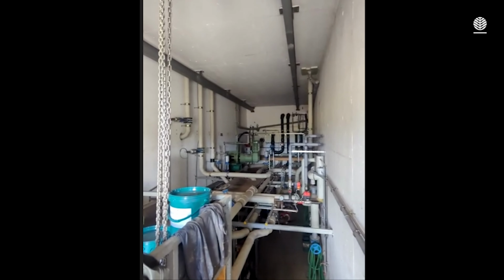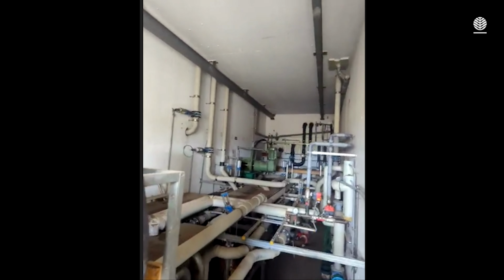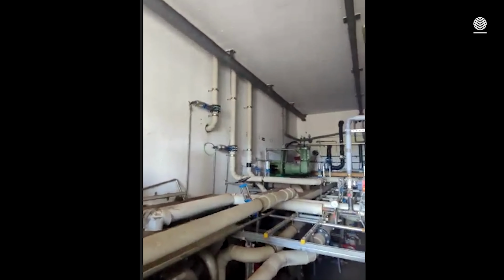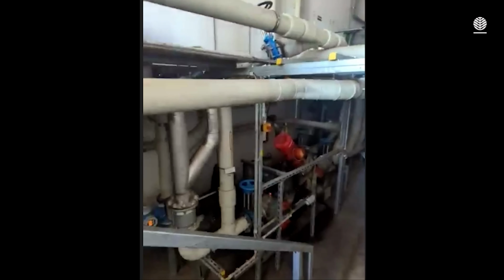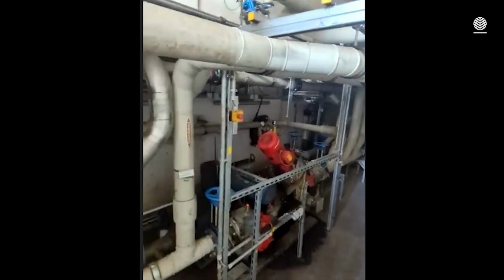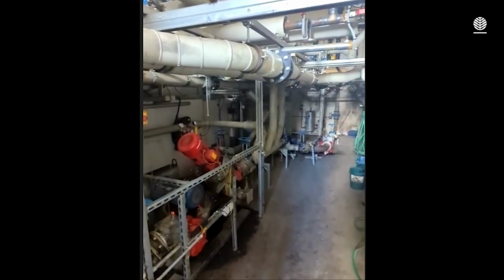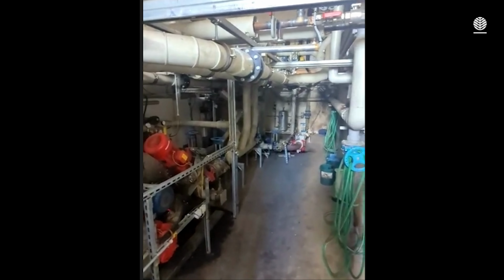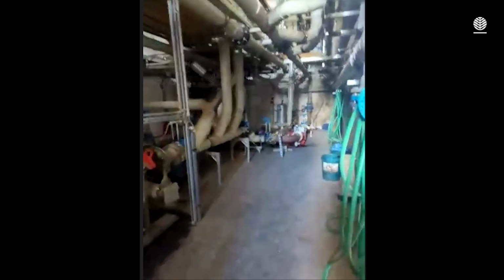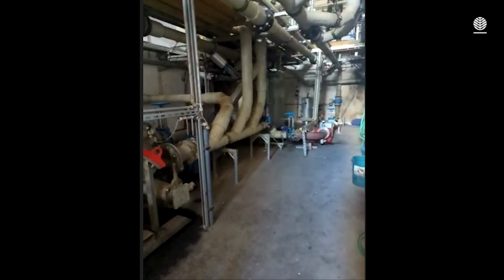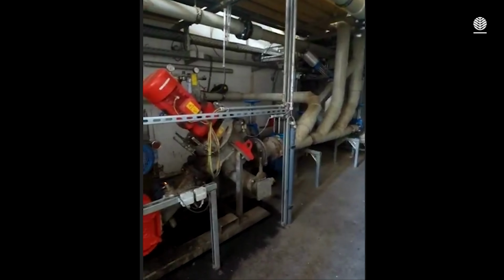I'm not sure you can step down. Go down the stairs, please. Then we'll find some pumps to manage the substrate. One pump is to feed the dewatering, the separator, and the other is for the heating circle. There's a small chopper installed. While we pump it to be heated, we chop the fibers to smaller parts and we are able to take out more biogas.